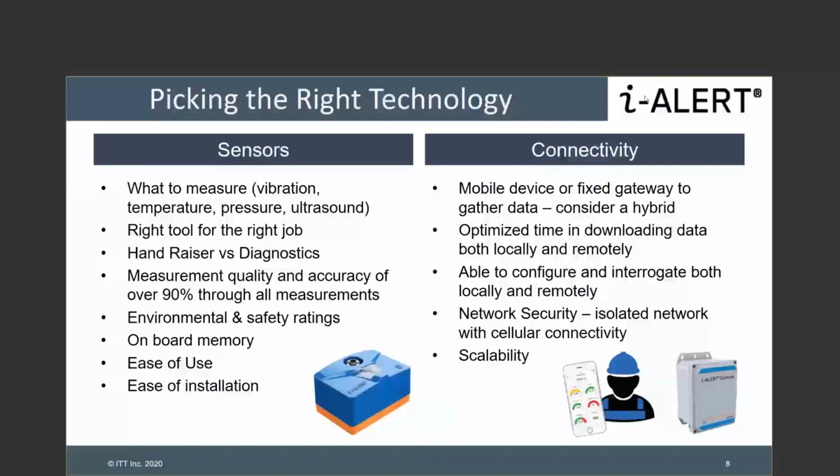It's good to have an idea of what is happening right at this very moment, but to get a full idea of the overall system and how it behaved before it went into an alarm state or after, it'll be great to have a trending analysis tool. That gives vital information to, first of all, evaluate what went wrong, whether it was a process upset or an actual mechanical fault, but also in the future to predict if a similar fault is seen on similar equipment. So those kinds of tools will definitely help if you can trend that measurement, whether it's vibration, pressure, temperature, whatever it is.